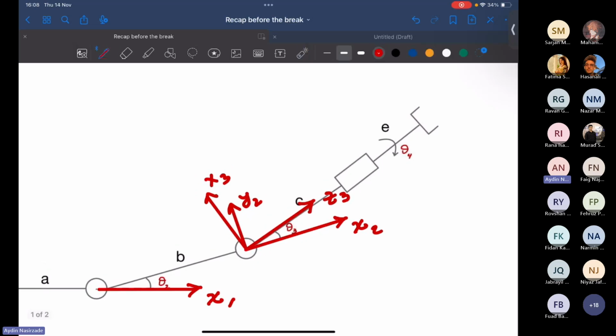The end effector frame, which is basically the copy of Z3 in this direction. Z4. What about X4? It should be perpendicular to Z3 and Z4, and it should intersect the extension of Z3. I think it'll do the job. Oops, X4 is parallel to X3, obviously.